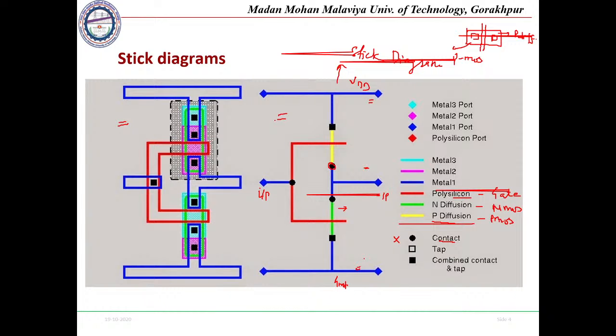If it is having fewer parasitic capacitances, it will give you similar results. We will be analyzing with respect to your schematic, that is schematic analysis. While doing the analysis, we do pre-layout simulation and post-layout simulation. Post-layout simulation is considered once we have designed the layout, after extracting the parameters and the different parasitic capacitances and parasitic components. We consider the parasitic components and then analyze the circuit, which is called post-layout simulation.